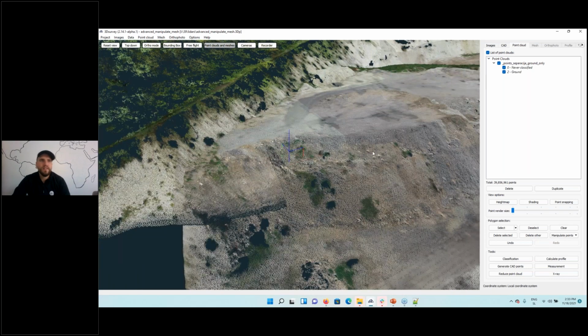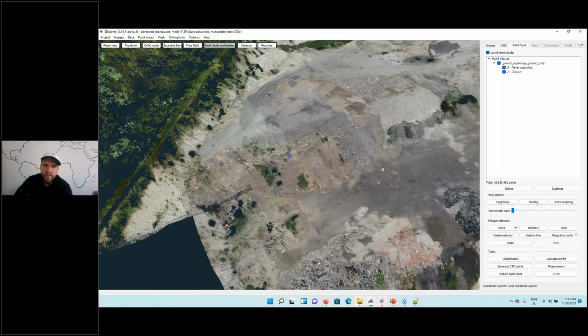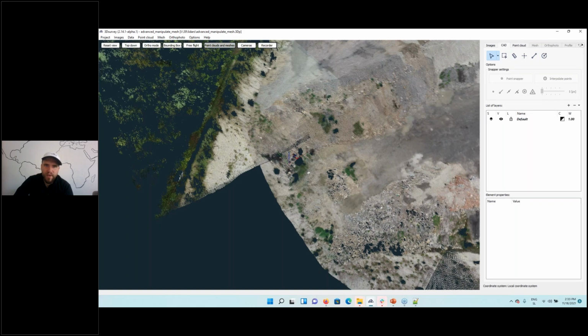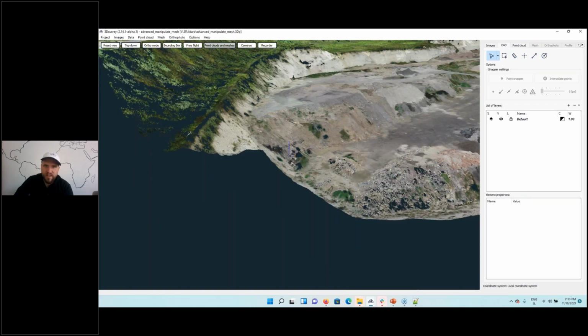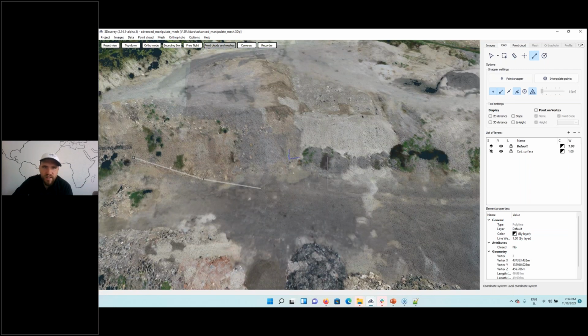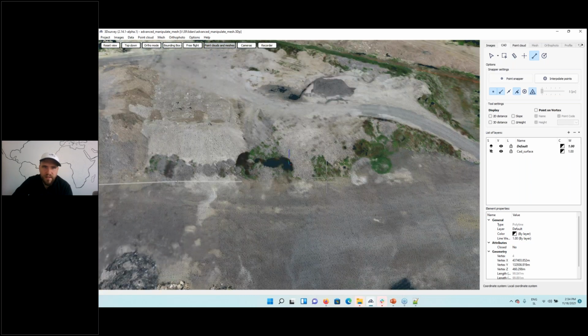We can now use the Triangulate CAD data function to generate the bottom surface for this kind of area. So how do we do that? We will go into CAD and we will draw the boundary of this area of interest. Like here, CAD, and we'll just name the layer CAD surface, for example. Okay, and I will just quickly draw the outline of this pile.